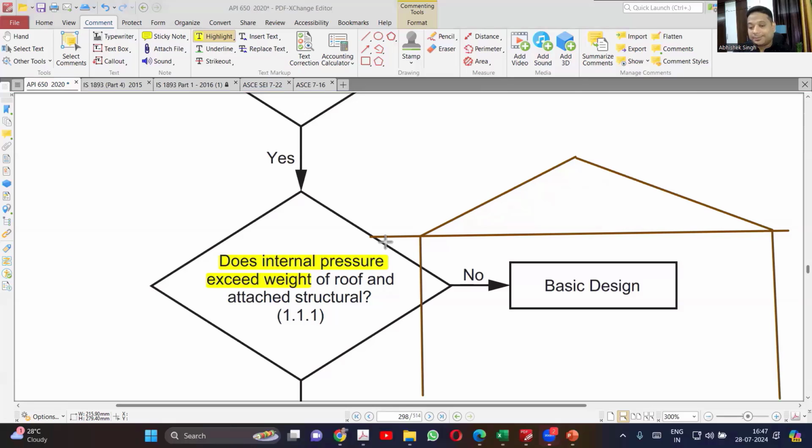Now let us put some highlight here on the frangible roof. The roof joint will fail prior to the bottom. When we say frangible roof design, we are saying that this joint between the shell and the roof will be weak compared to the joint between the shell and the bottom plate. Normal conditions will not cause it to break.